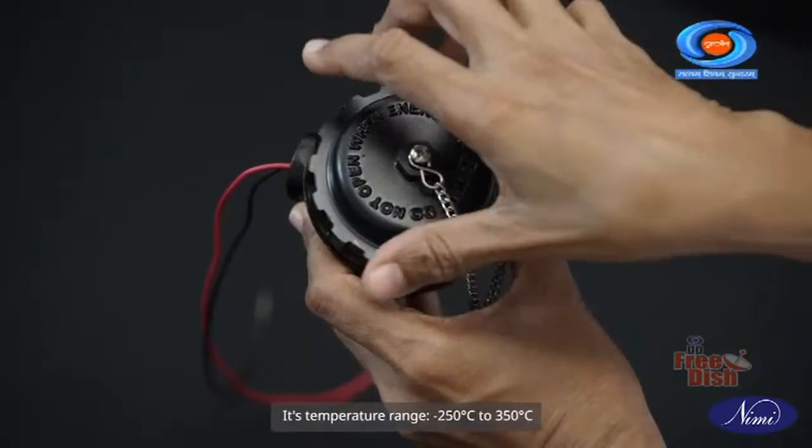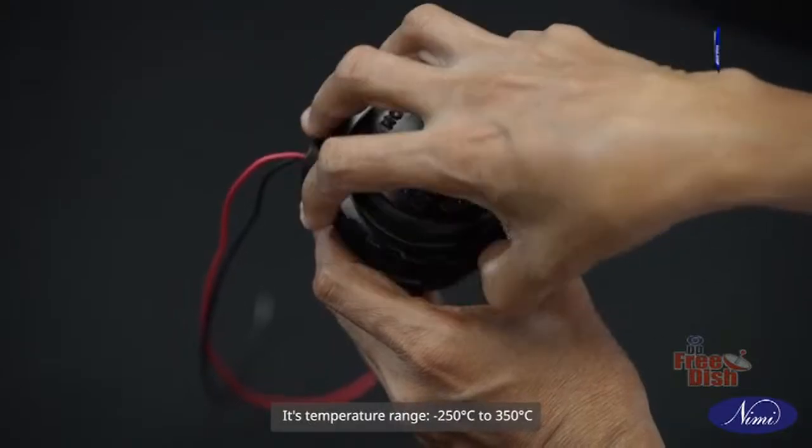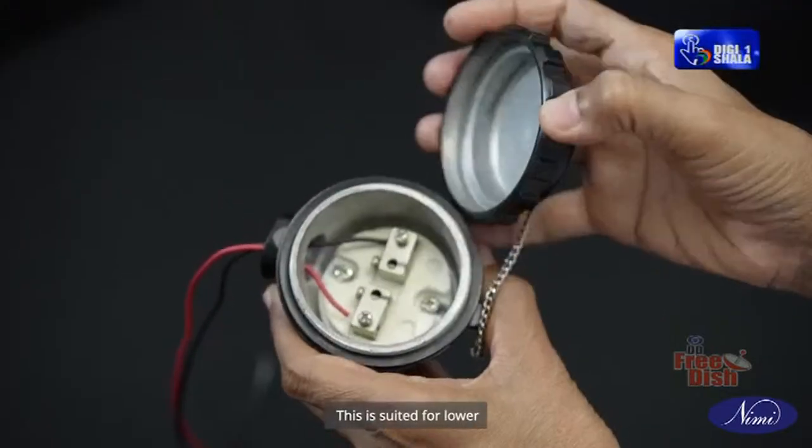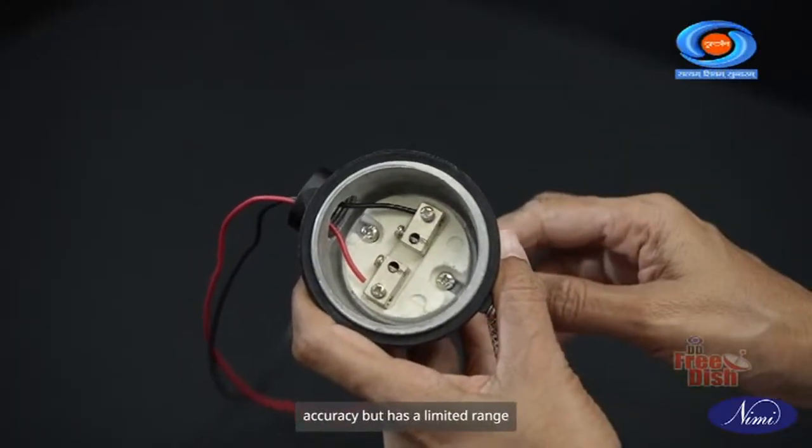Type T, its temperature ranges from -250 degrees Celsius to 350 degrees Celsius. This is suited for lower temperature applications and offers good accuracy but has a limited range.